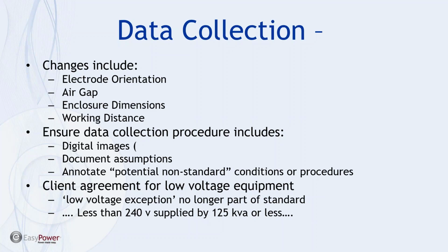the low voltage exception has been removed from the standard. In the old days, anything less than 125 kVA as far as the energy supply in low voltage, less than 240 volts, could be excluded from calculations. That's no longer part of the standard, and I'm not going to cover those details here, but I'm just saying you need to make sure you have some sort of agreement with your client, because that could impact the number of buses that you're having to collect data on.